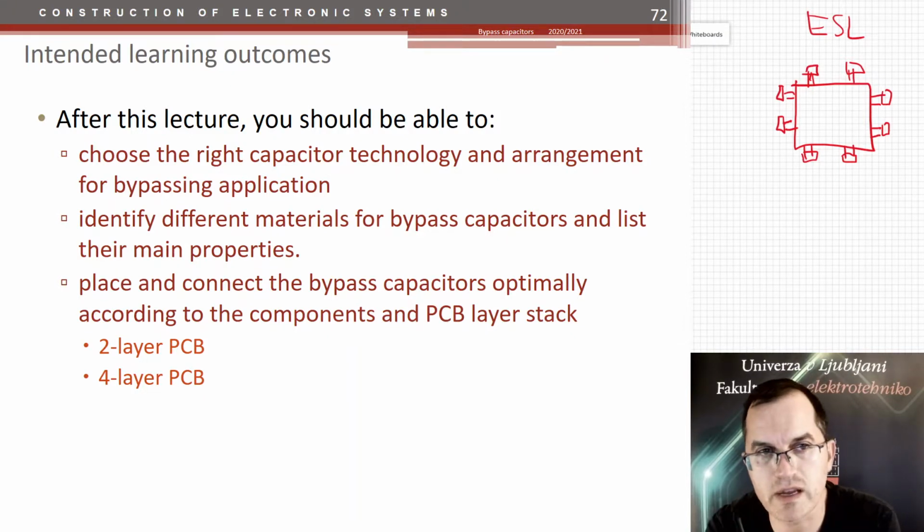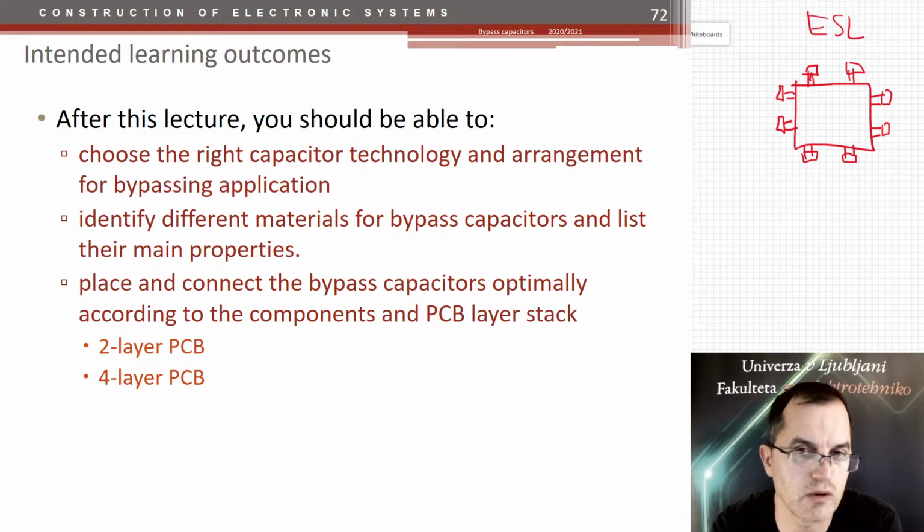And then all the rest, let's say tantalum or electrolytic capacitors, are acting as bulk capacitors to minimize the impedance of the power supply at low frequencies, and also as damping capacitors, which are lowering the quality factor of the parallel resonance frequencies which can occur because of the combination of different values of the capacitors, and of course the inductance of connections.